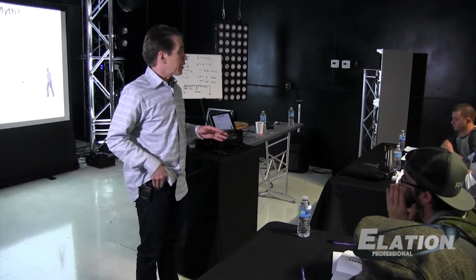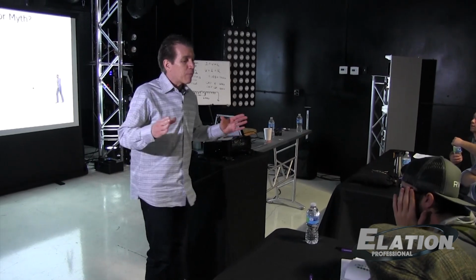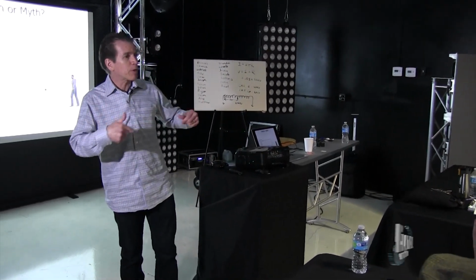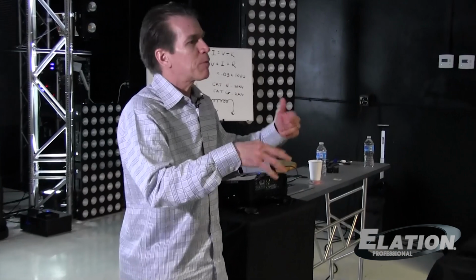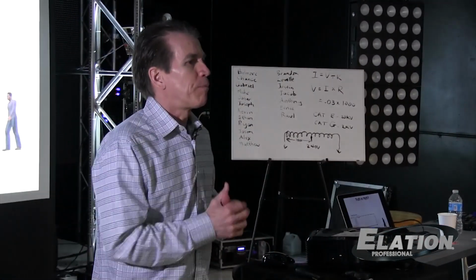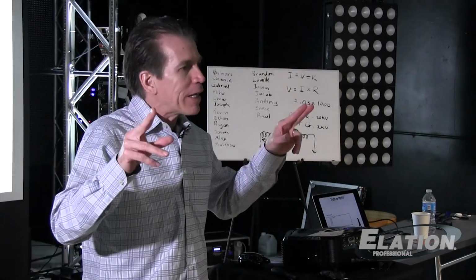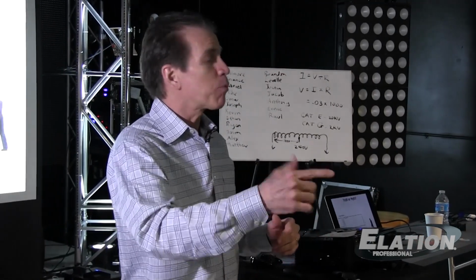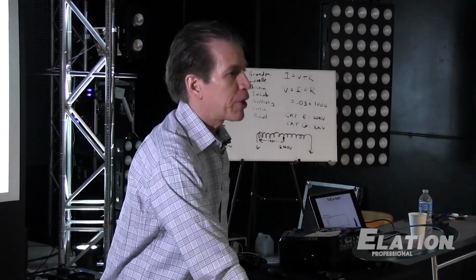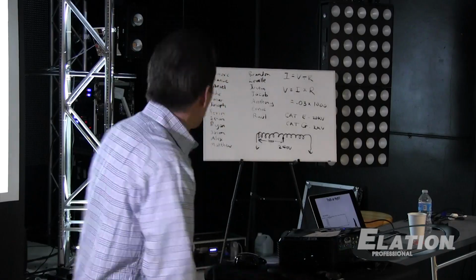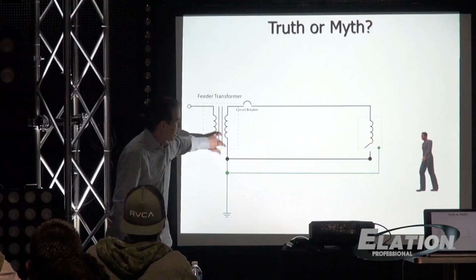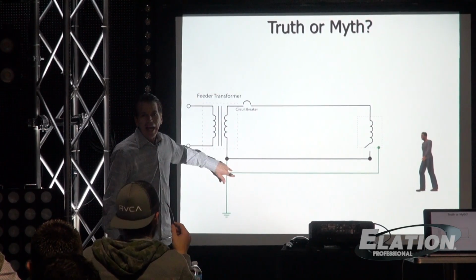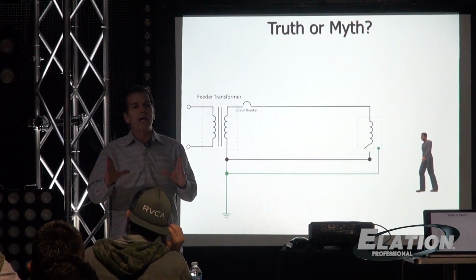Here's what happens. This happens a lot in the film industry. So they have what they call honey wagons, or the trailers where the stars go and get ready, or they're resting between their takes, or they're getting ready for their shot. They're relaxing in their mobile home. Well, these honey wagons are designed to be self-contained, so they have their own portable power generator in them, like a little putt-putt generator. And so the generator is the supply, and the neutral and the ground are bonded at the panel of the honey wagon.